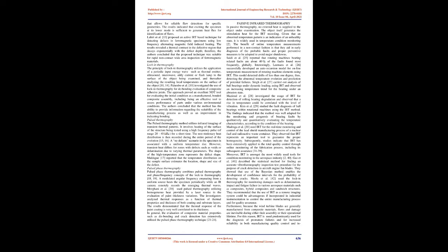Lahiri et al. proposed an active IRT-based technique for detecting defects in ferromagnetic specimens using low-frequency alternating magnetic field-induced heating. The results revealed a thermal contrast in the defective region that decays exponentially with the defect depth. Therefore, the authors concluded that the proposed technique was suitable for rapid non-contact wide area inspection of ferromagnetic materials.